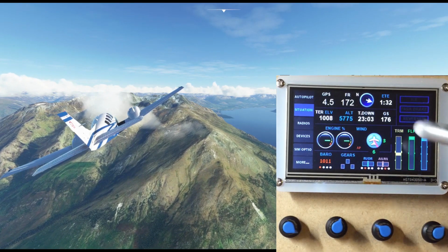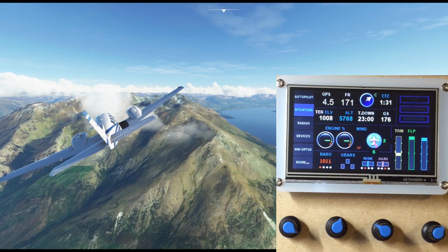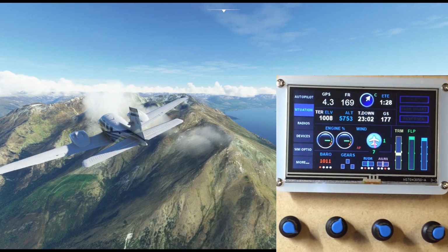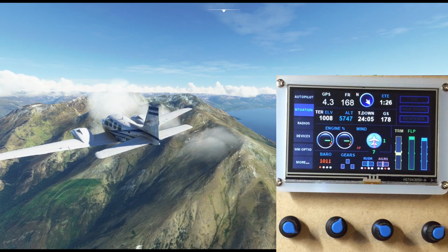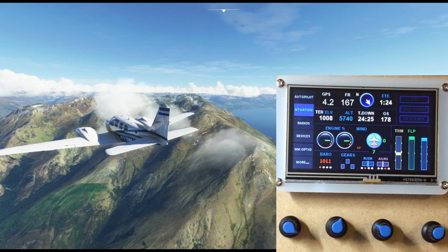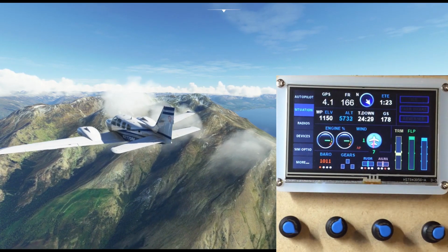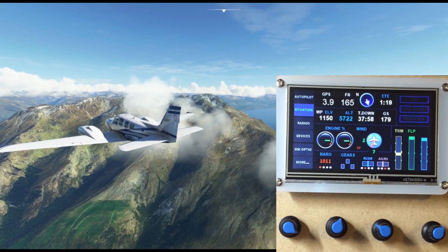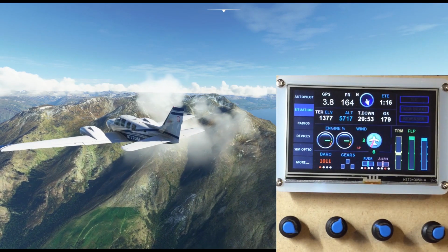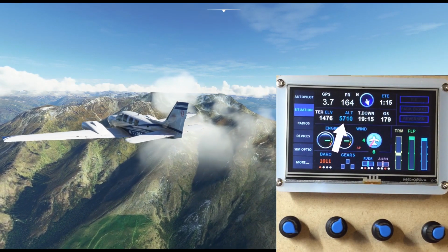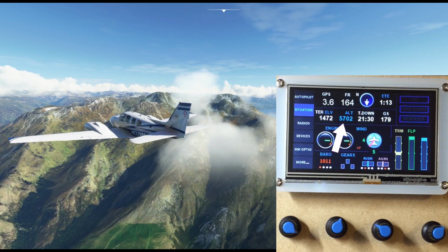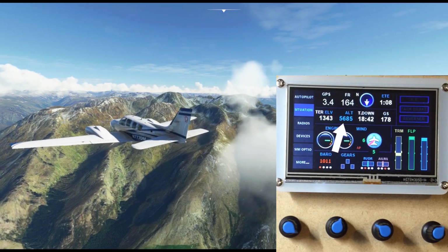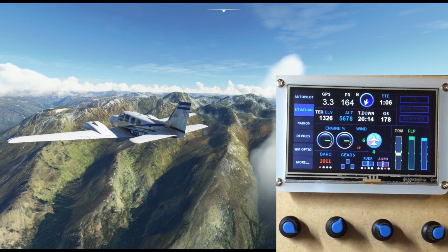Therefore, with this information here, the old navigation page is gone. And for the arrow display, you can also switch between the relative bearing and a regular compass by touching the dial. On the second row, this is for the terrain elevation. If you have a valid GPS waypoint, you can switch this to see the waypoint elevation. It's between altitude of your aircraft, and if you are below 2500 AGL, the radar altimeter.